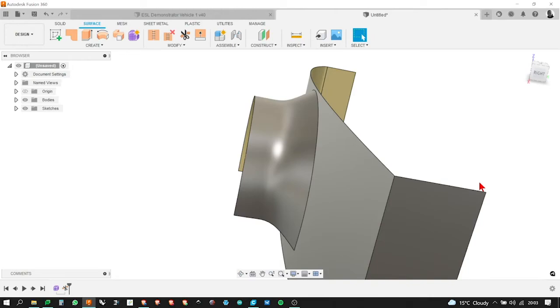If your wheel trim went all the way down, so the interior of the wheel trim was its own element, essentially, would you use the trim tool again? So you trim the curve to the body. Exactly. That's what's known as overbuilding in surface modeling, where you create surfaces which overlap each other, and you're trimming one way, you're trimming the other way, and you'll keep on trimming until you get the one surface that you do want.